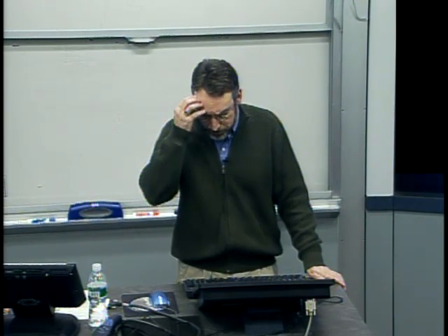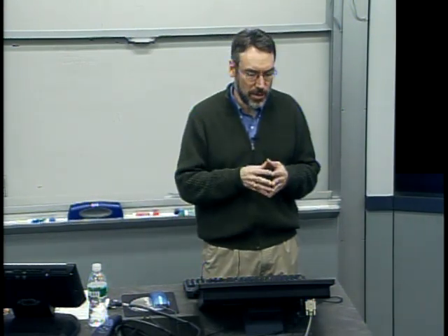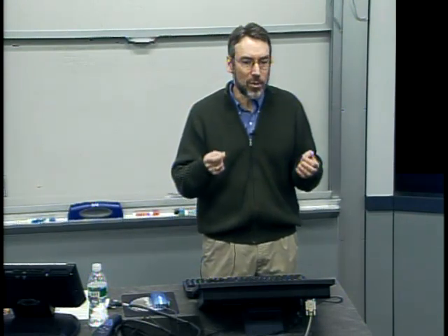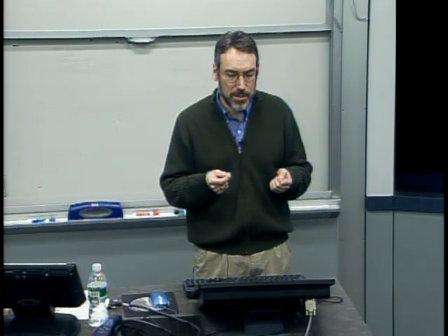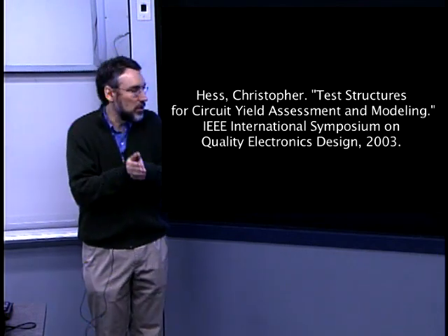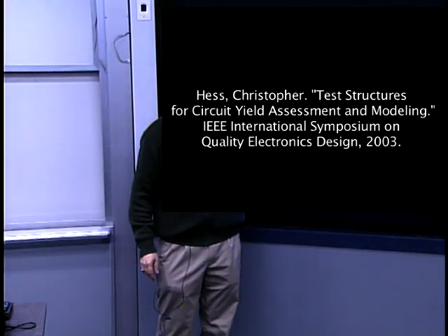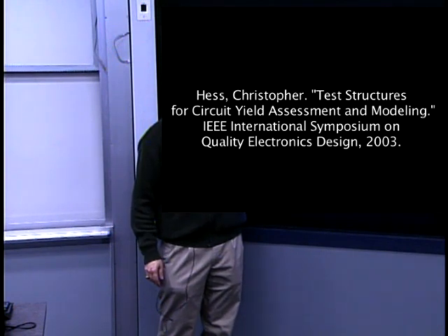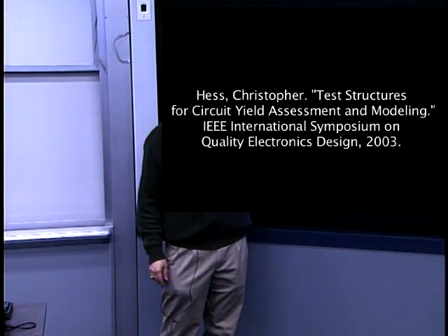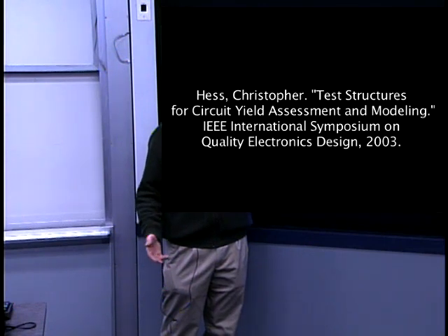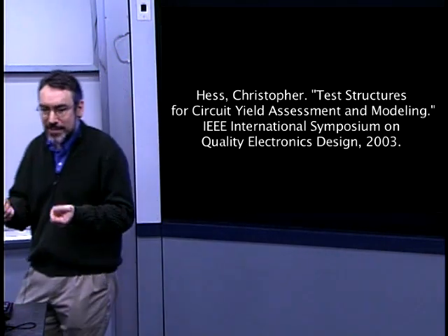Now, I mentioned this a little bit last time. It used to be 10 years ago, 15 years ago, if we talked about yield, the percentage of functioning devices that came out of a semiconductor fab, the main worry limiting yield was particle defects. And you can imagine we're talking about very, very small features here. And if pieces of extraneous matter were to fall between, say, two metal lines, that would cause an electrical short, or could cause an electrical short, and now the device does not function. It does not function correctly.